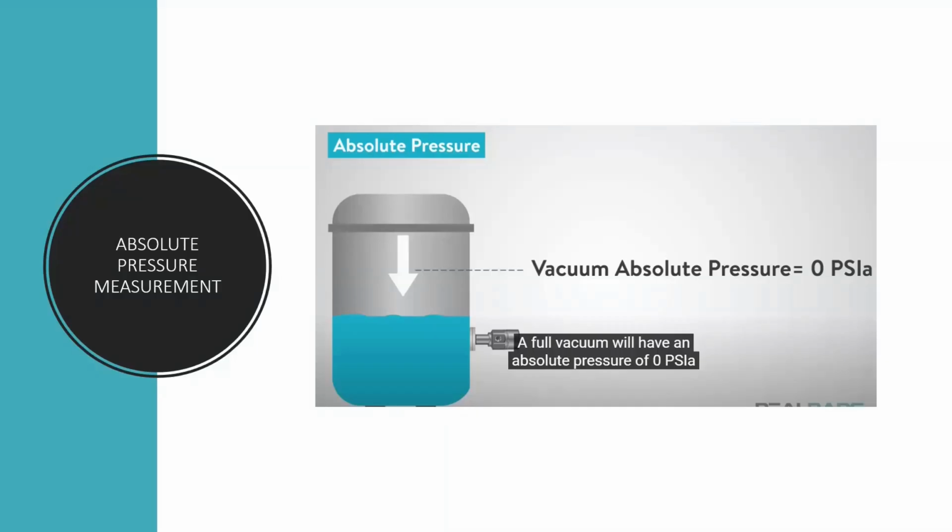In industries, we use this, for example, in places where we want to extract air, like in vacuum pumps. For those in alcoholic beverage manufacturing, like in filling and packaging, in the process of evacuating air from a returnable glass bottle, we suck out the air because the filling process doesn't have to take place alongside air inside. So we need a good vacuum, a negative value. In this case, we use this kind of sensor for vacuum pumps.